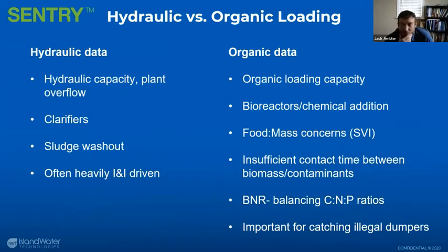Just to kind of separate the two, I think both of these are very important pieces to measure in this collection system. You've got hydraulic data and you've got organic data. Hydraulic data tends to be hydraulic capacity for the plant. So that's plant overflow issues. Are you going to overflow the plant? Are you going to force too much liquid through these clarifiers?